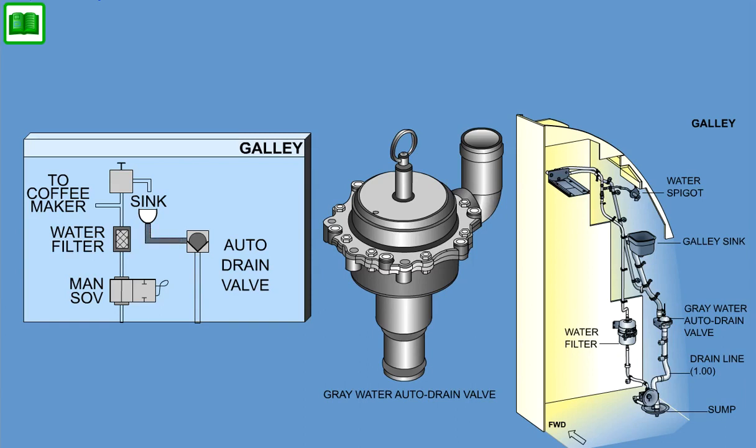In flight, the valve remains in a closed position until there is a head of wastewater at the inlet. The valve then opens automatically in order to drain the wastewater. The drain may be opened manually by the cabin attendant in case of a clog. The ring handle at the top of the valve is pulled up to open the valve seat and clear the line.